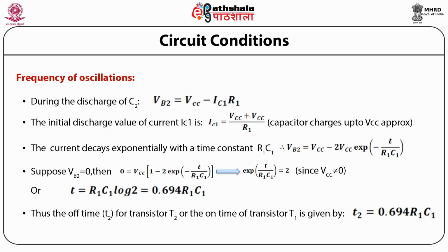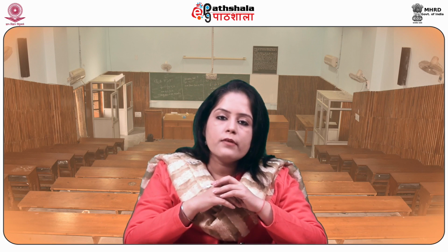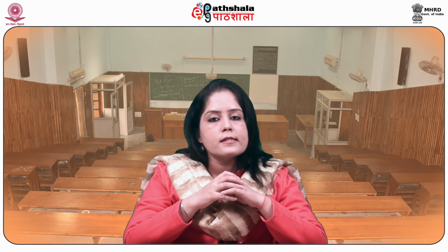0.694 R1 C1. Similarly, the off time T1 for transistor T1, or the on time of T2, is T1 equal to 0.694 R2 C2. So the total time period will be T equal to T1 plus T2 equal to 0.694 times R1C1 plus R2C2.